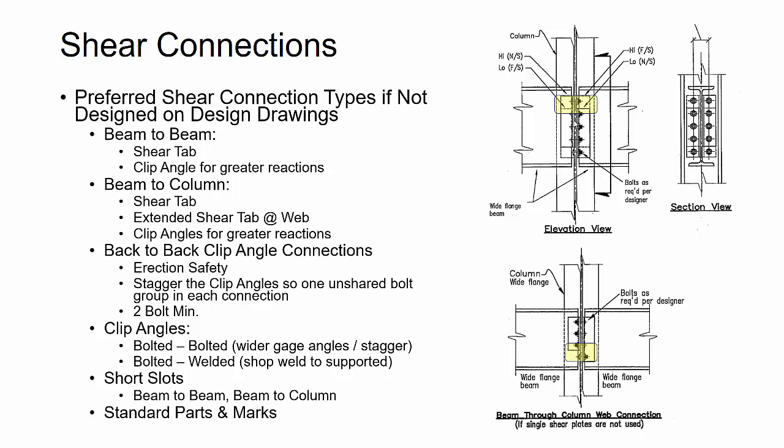If you do have a project where you have standard parts, including standard part marks, you can set those up both in STS2 and Tekla. So that way, anytime you do the modeling of those pieces, it'll actually use those piece marks. And then if there's something that's unique on the job or job specific, it'll take a regular standard submaterial part mark.